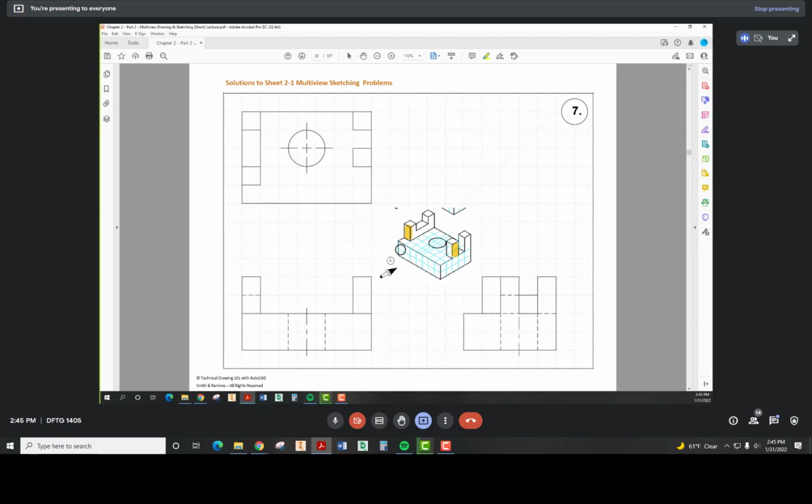This is my primary view, so I can touch this plane. I can touch these planes. So I've got this plane here, and it is a complete rectangle, and then behind that we have these castle blocks. So we draw our visible edges in first. I've got to have the top view for that hole. I've got to locate it and say what size it is, where I can touch it. So I've got to have this one.